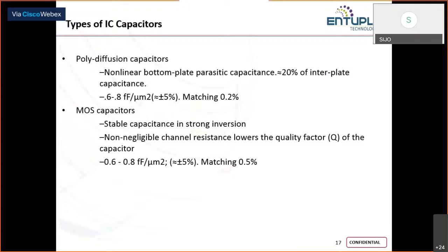That is the one we used yesterday. I think if you remember, we used a 3-terminal NMOS cap as the compensation capacitor in your 7.5 op amp. So there was a 3-terminal NMOS capacitor. Obviously we are making use of MOSFETs, active devices, to realize your capacitor.